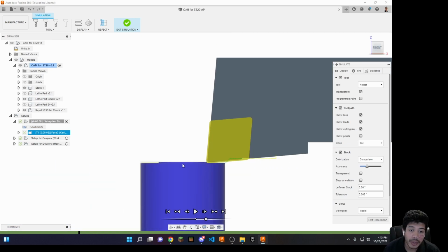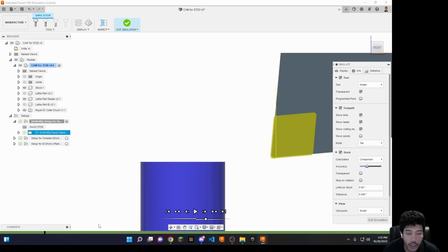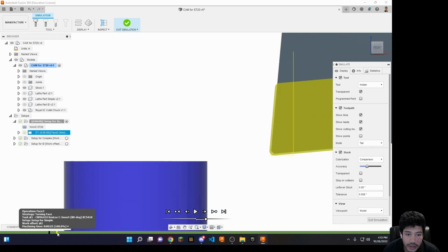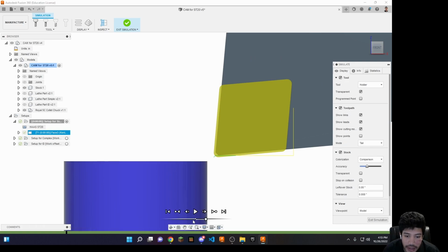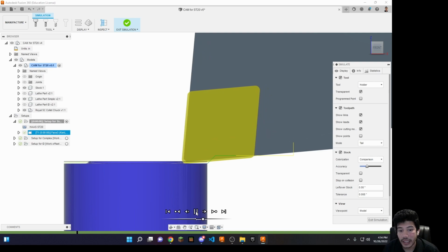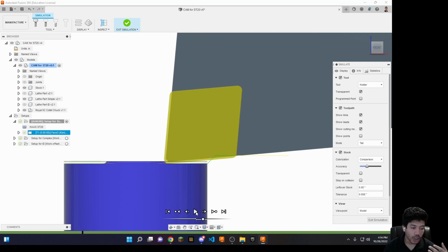Now there is another behavior here that I don't like. You're on the machine, everything looks lined up, and suddenly your tool takes a small dip into the material. This is not going to be helpful if you're looking at the tool and looking at your stock and anticipating that it goes straight forward, because it'll go down and cut. And that could mean that you could miss a potential crash if you didn't account for it diving down.